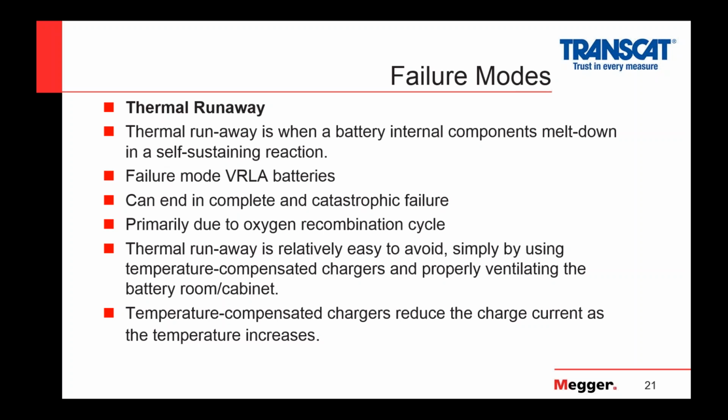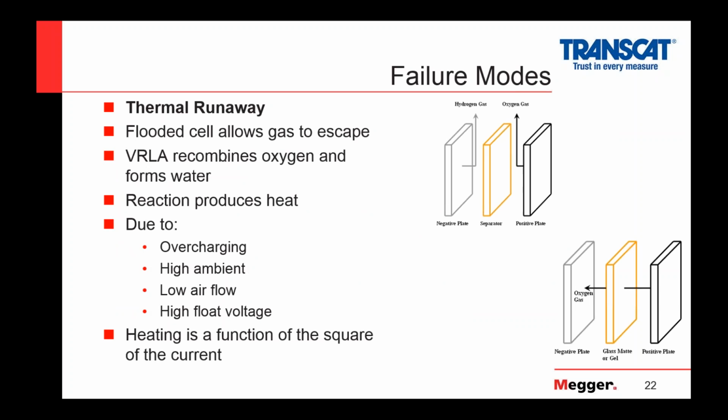And the problem with the thermal runaway is it's only going to end in one of three ways. It's going to end in either a meltdown, a fire, or an explosion. So we want to always be careful with this. Now keep in mind, a thermal runaway is not going to happen overnight. In fact, I've heard a lot of people really call it a thermal walkaway because it is slow, and as long as we're monitoring our float current, we should be able to see it.